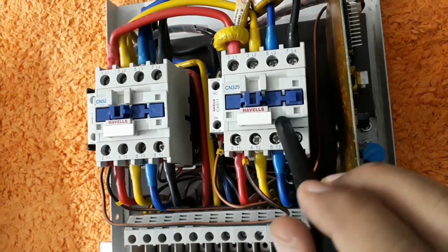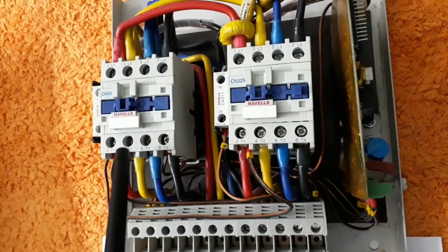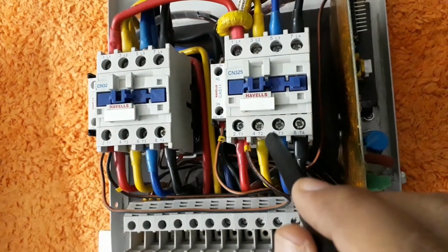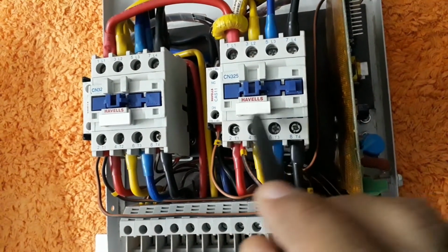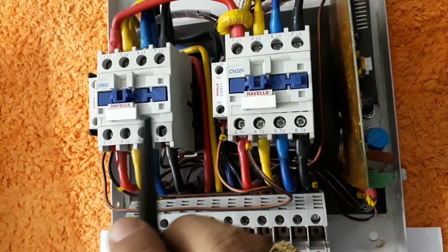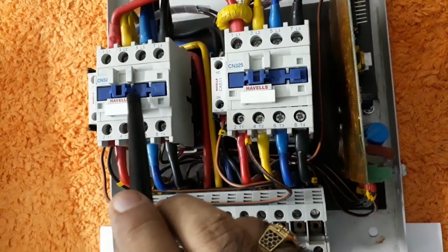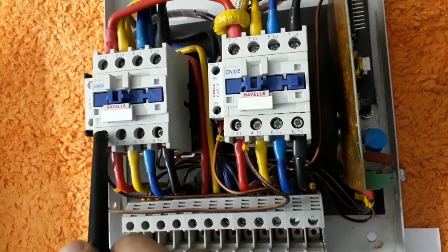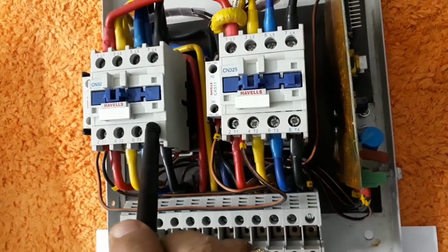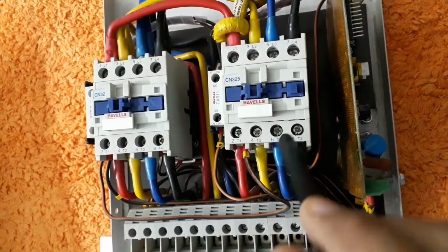During the rainy season or during the summers, there will be a lot of dust accumulation here. During the rainy season, that dust absorbs a lot of moisture, and when this is switching on, it creates a problem in the connectors. Then your relay starts fluctuating. It is not connecting properly, and it starts fluctuating. That is what happened with my ACCL.